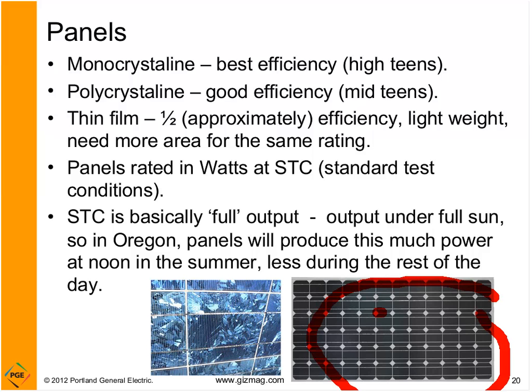The little empty spaces in between the little chips, or the little pieces of silicon, are because these pieces came from circular cylinders that were sliced to make the wafers. So you can, at a glance, say this is monocrystalline just because it has those openings between each of the four sub-chips that are in the panel.